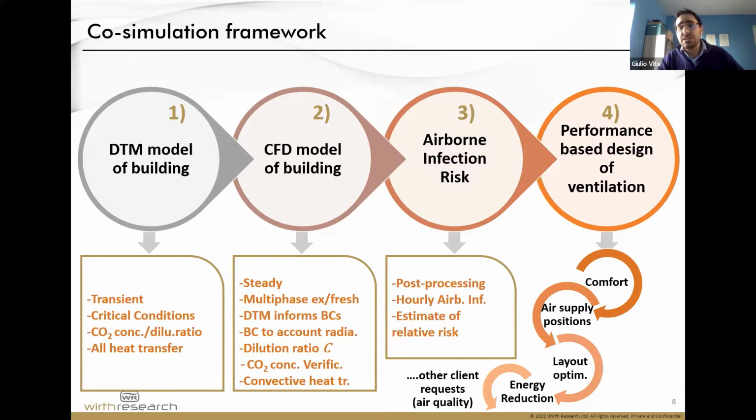We can also use DTM results to verify the CFD solution, meaning that the CO2 concentrations, for example, can be a great way of making sure that both simulations tell the same story. And then we come up with an airborne infection risk methodology to estimate the infection risk, which is relative for your building. That's the way we formulated it. The performance-based design of the building, of the ventilation system can then take place.